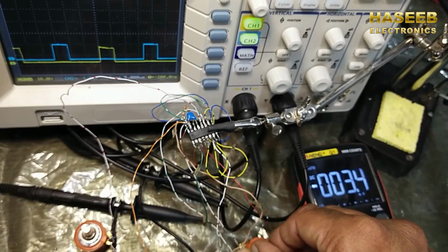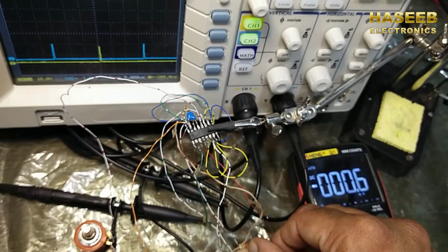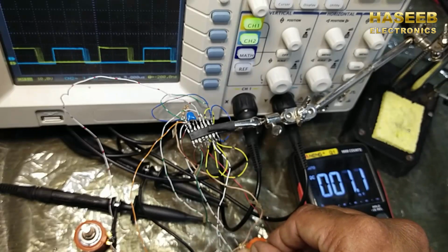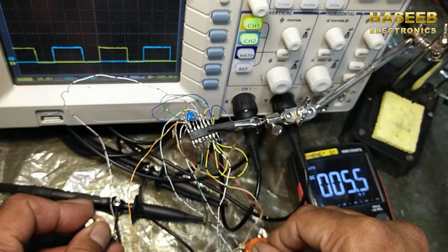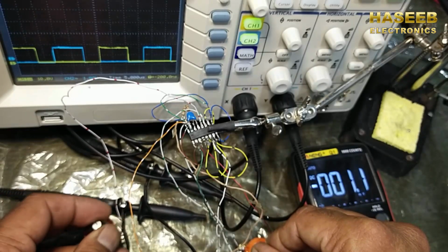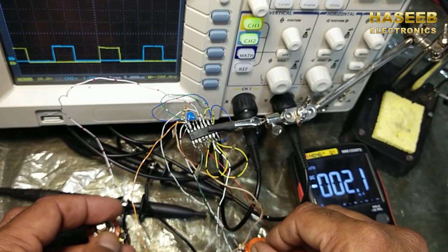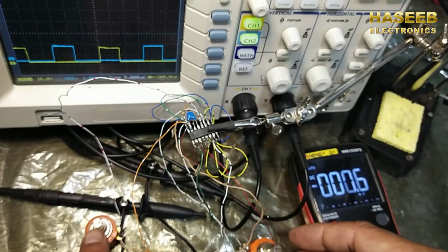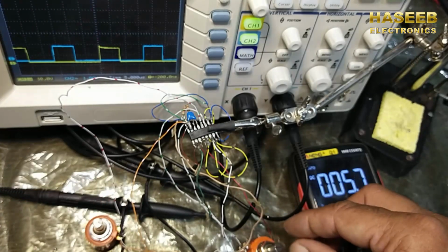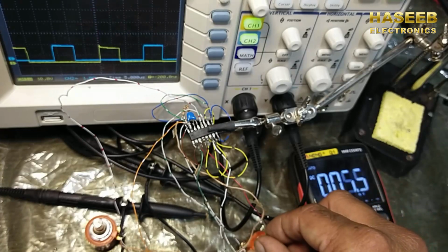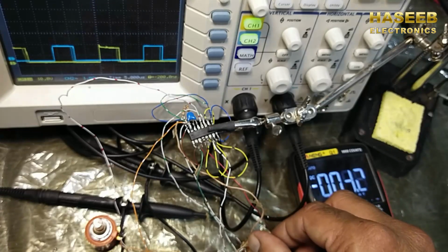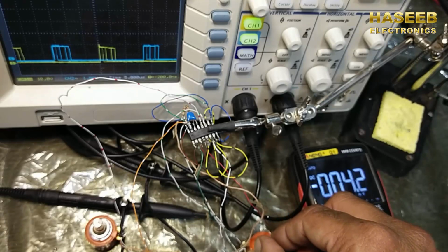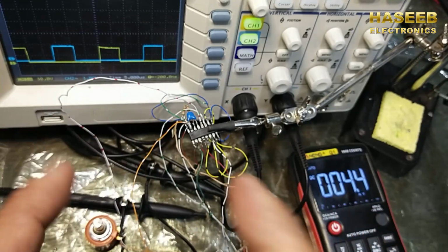So it controls the duty cycle. It controls the duty cycle, but this function controls the dead time between two channels. If we limit the dead time here, this is for protection. Now the duty cycle will only work between this limit. So this IC will work in a narrow window.